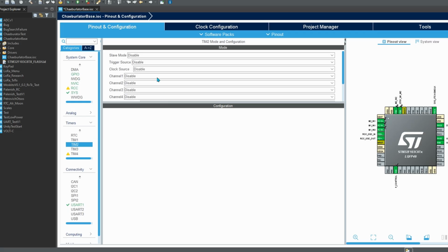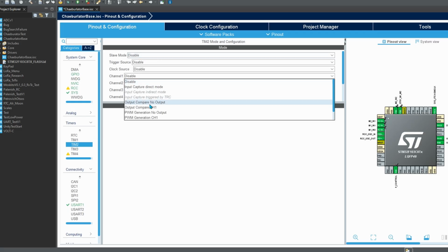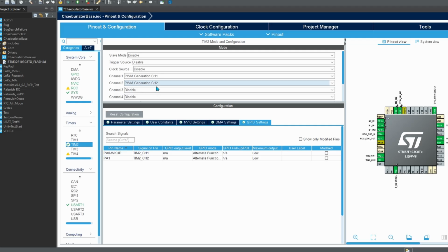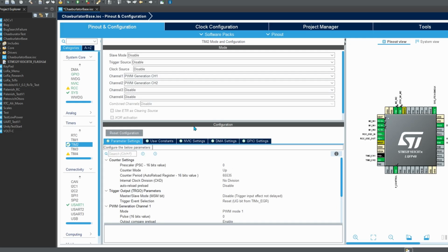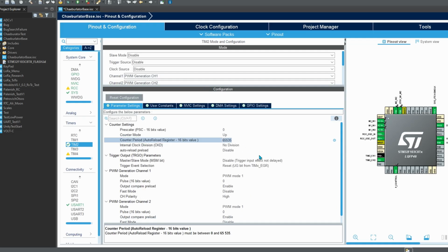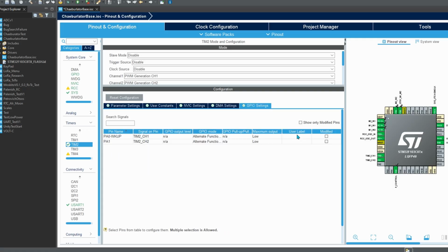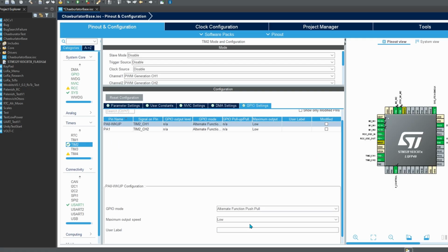We will use a timer to add 2 PWM channels for each motor. We will set the fill width, that is, in this case, the motor rotation speed. Don't forget to specify the frequency. I am using 10 kHz. This frequency doesn't exceed the frequency specified by the TB6612 manufacturer. Setting it above 15 kHz is not recommended, as it will lead to excessive losses.